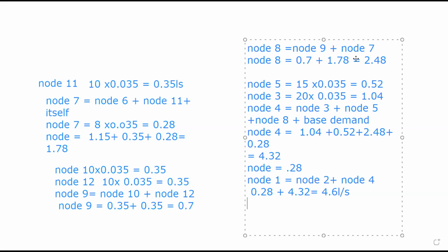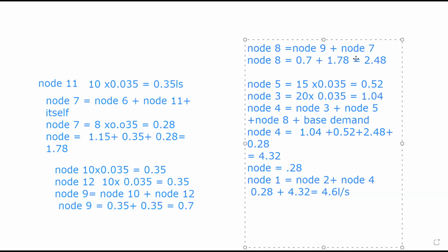Okay. Last week, I trained people from water resources, and I told them something that we do in reinforcement. If you want to calculate the quantity of reinforcement, the only thing you need to do is calculate the concrete volume you need. You don't need to start doing a bar-bending schedule or asking for structural drawings.